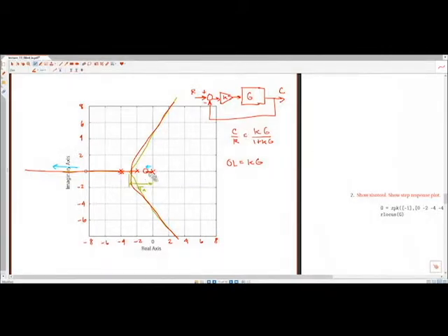Okay. All right. Any other questions about these two branches of the root locus? Ben. So, like ideally, say you're increasing k in this situation, you still wouldn't want that cancellation, right? Because your system would probably be unstable because it crosses within the right-hand plane of your other pole. Okay, yeah. So just to rephrase that a little bit, if we wanted to get a perfect cancellation, that would mean we have to increase k to be infinity, right? And so you're saying that we have two branches here that if we increase k to be infinity, these closed loop poles associated with these two branches will be in the right half plane.